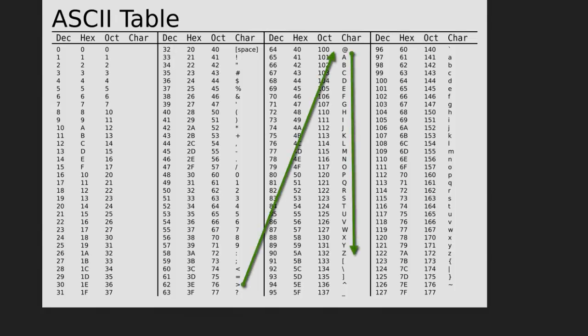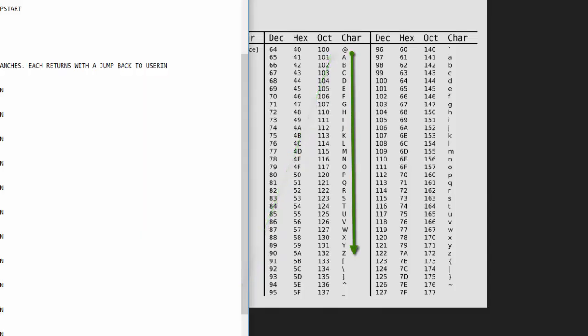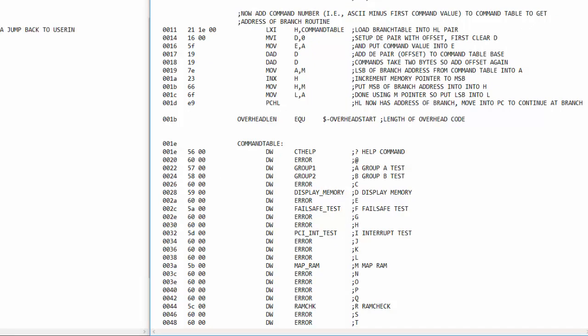So in a sense, that makes it more efficient as the command table grows, because I counted that we had to have 3 bytes for each command, but our command table has to have 2 of those no matter what. So really each command only adds 1 byte to it as long as we're fitting within our command table. So we have to have all of those other bytes as overhead.